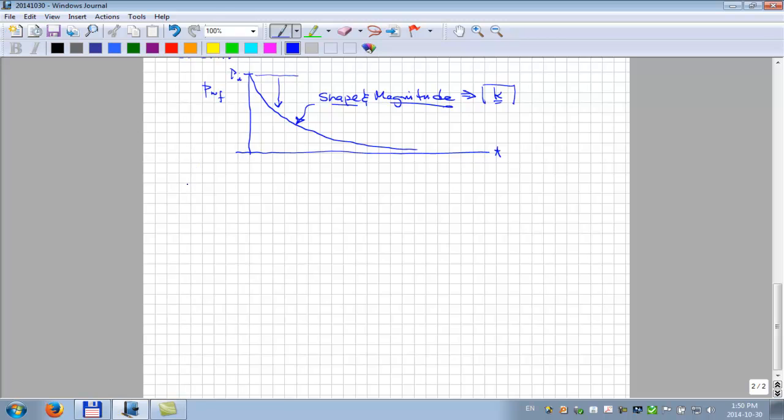So it ends up that every well, with basically that being constant, of course, you've got a lot of assumptions: low and constant compressibility, radial, cylindrical, all these assumptions.